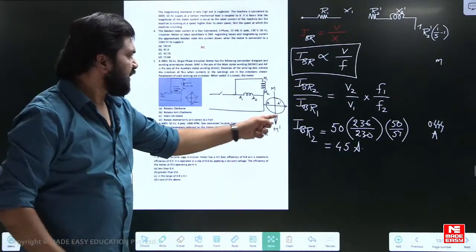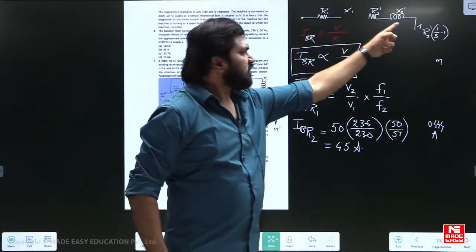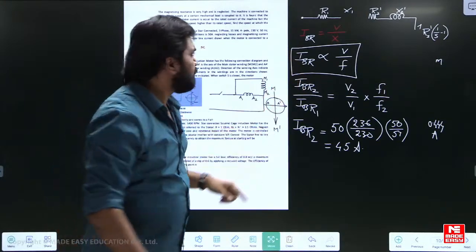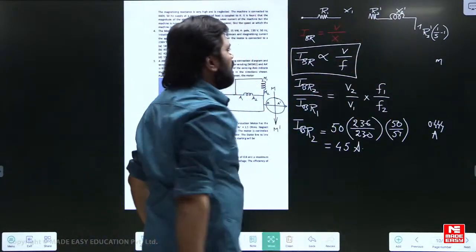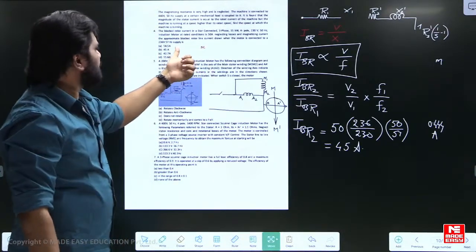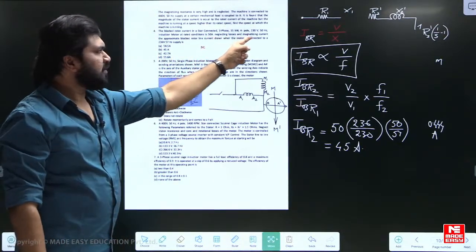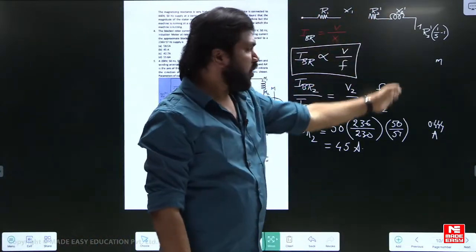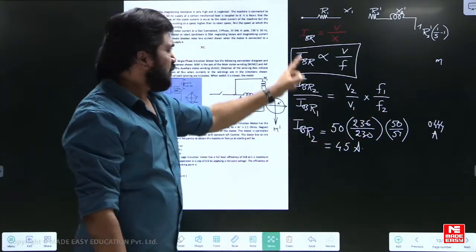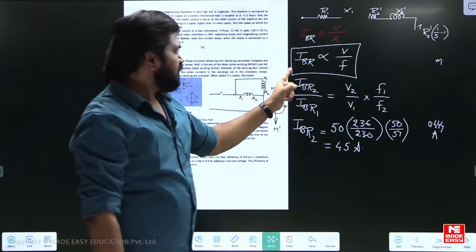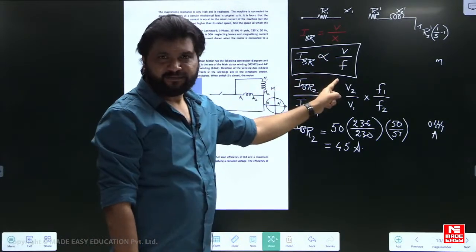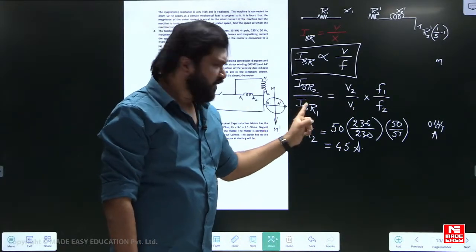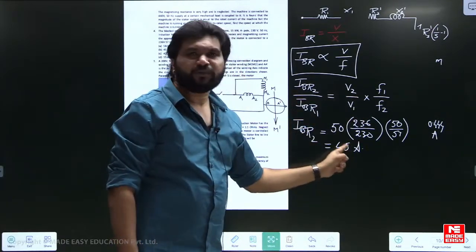Question 4, this is the hint. The equivalent circuit, no, this one. From the equivalent circuit of the blocked condition, don't say all this. It was given very clearly in the question: neglecting losses, neglect magnetizing current. So there is no R1, there is no R2 dash, only X will be remaining, blocked. S is equal to 1, short circuit. So I is equal to V by X, meaning I_BR is proportional to V by f. Based on this, you can write an expression like this. Simply, you can use this expression to solve question number 4.